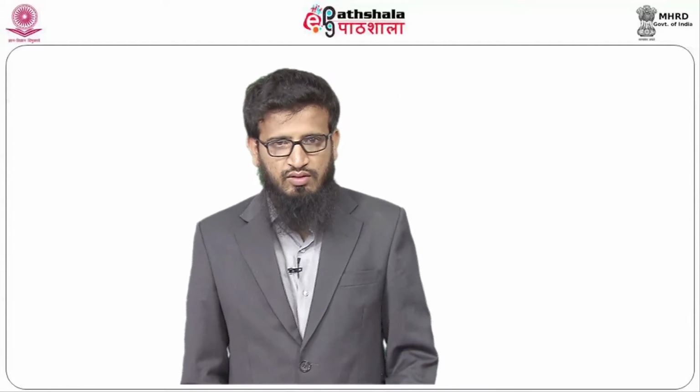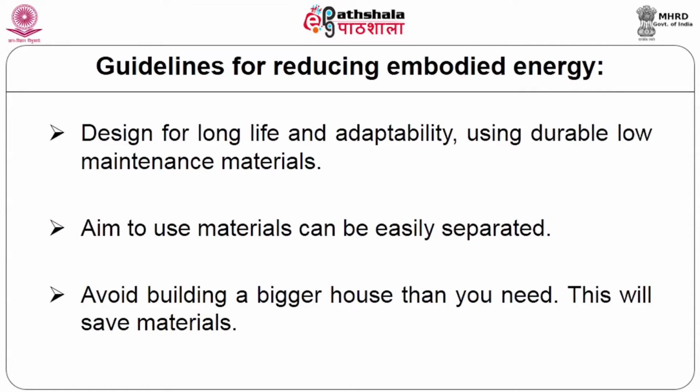Now, these are the guidelines for reducing embodied energy. Any designer, anybody who is designing buildings, after going through what embodied energy is, what the different values are, and how you go about it, it is important that we understand this, and to complete the entire module, we have put it in one single section called guidelines for reducing embodied energy. First one is always design for long life and adaptability, using durable, low maintenance materials. Aim to use materials that can easily be separated, which means that if you want to replace something, you can easily separate it rather than breaking the entire thing.